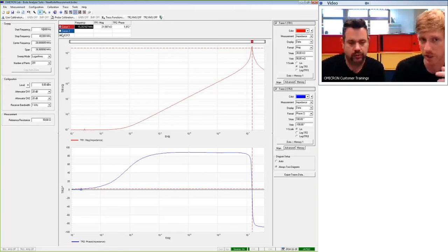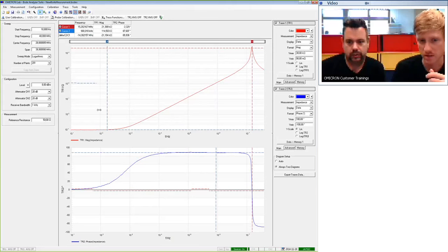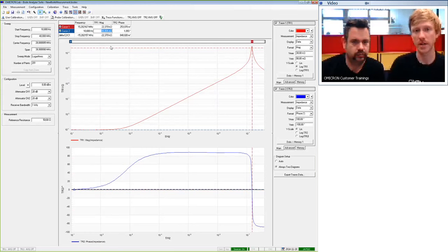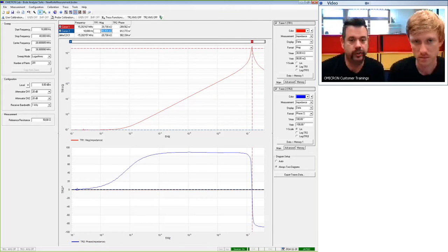And then we could measure the wire resistance. A very precise measurement you will only get with a milliohm meter or a DC ohm meter, because here on cursor 2 I have placed it at 10 Hertz now. It tells me 98 milliohms, or nearly 100 milliohms, and as mentioned before, this measurement is very accurate from half an ohm to 10 kilo ohms. If it's now 98 or 102 milliohms, this is not the right measurement to determine this. But later on we will show a measurement for low impedances.